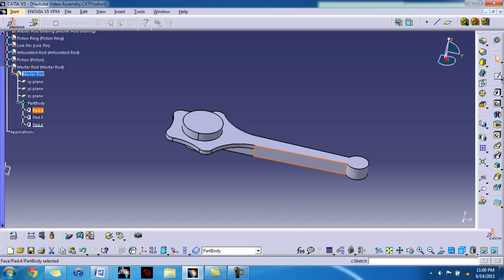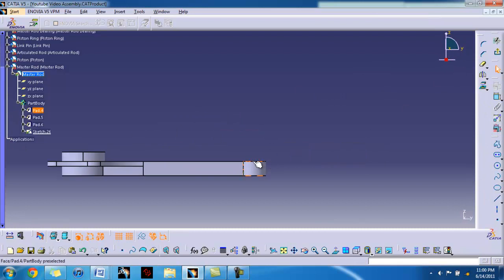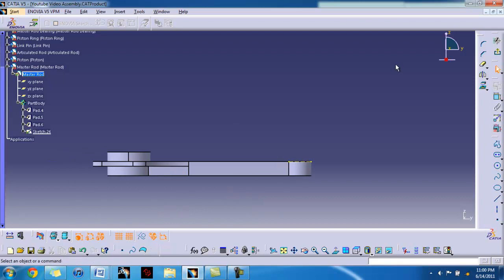You're going to go into the side right here, surface. Go into Sketcher. Now we're going to create the sketch for the groove with the radius. You're going to project this 3D element, but we don't want to use the line, so we're going to make a construction line down here at the bottom. Make sure that's clicked orange. Now re-click it so the rest of your sketch is in a construction line.